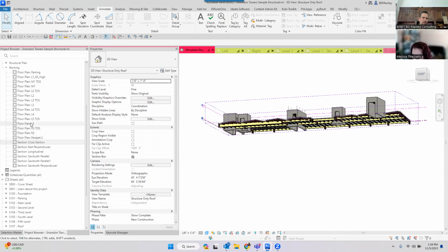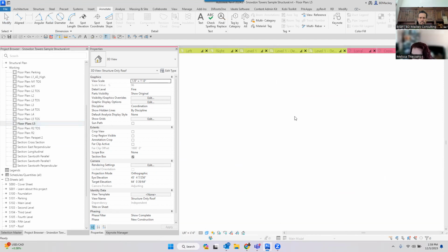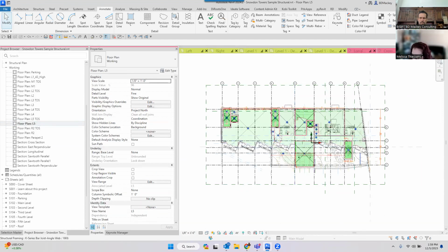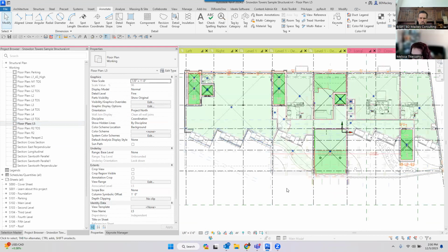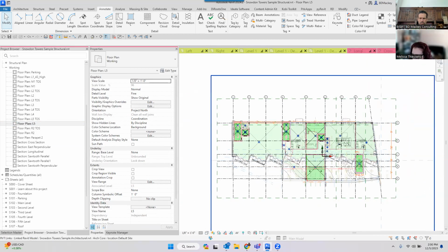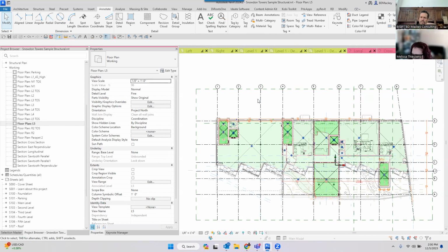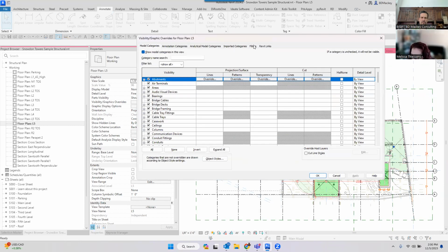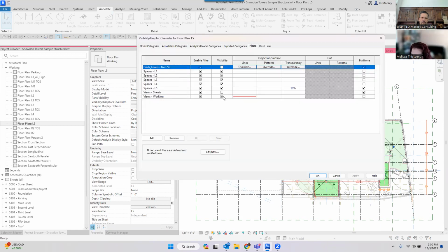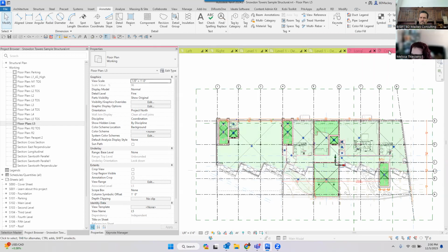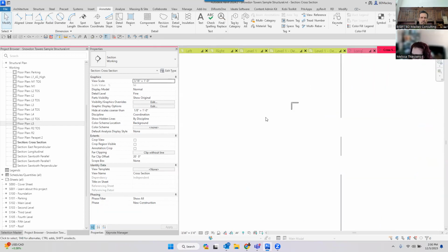We'll just go to the L5 view and I'll find that cross section. Do I have sections? I'm wondering if somebody rotated it and now your detail items are associated to that, and so now you can't. What filters do I have? These are on. Why am I not seeing it? I thought I knew this cross section. What's my height of scales coarser than 1/8? That's probably what it is.